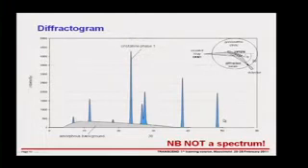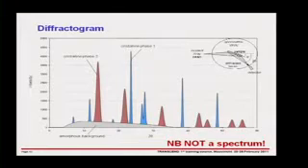So if, for example, you had this first crystalline phase here, and then another crystalline phase here, if they have peaks that are well separated, you can distinguish one phase quite easily from another, and you can, by measuring the relative heights of these peaks, determine how much of crystal 1 and crystal 2 you have. So this is a very well-established technique.